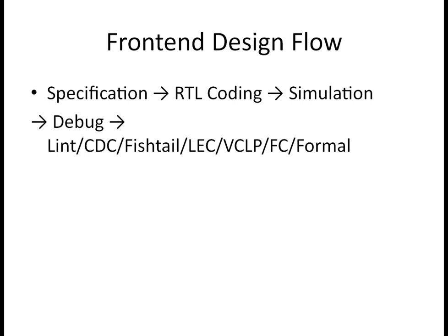One more condition for inferred latches is when you have not mentioned the full case. In a case statement, suppose you have taken a 2-bit select line, and out of 4 conditions you have mentioned 3. In that case also the tool will infer latches. Either you have to write all the cases, or if you are mentioning 3 conditions using the case statement, then you need to write default also. Then the tool will not infer a latch issue.